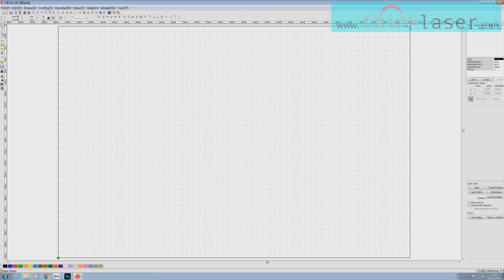We'll click on the line, and that's the thing. You can't keep using the same line again and again. You have to keep going to select it, which is a bit of a nuisance. So we've dragged it onto the page, and really all we need to do is we don't need to hold the mouse button now. We can just click. All right, and that pins it down at one end. We can move it around wherever we want. And now we can use the control key if we wish, and the control key will make it move in just the ordinate horizontal and vertical positions.